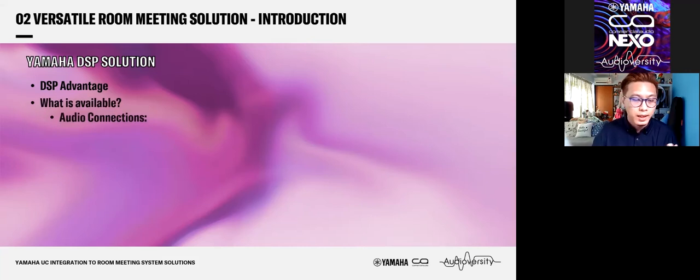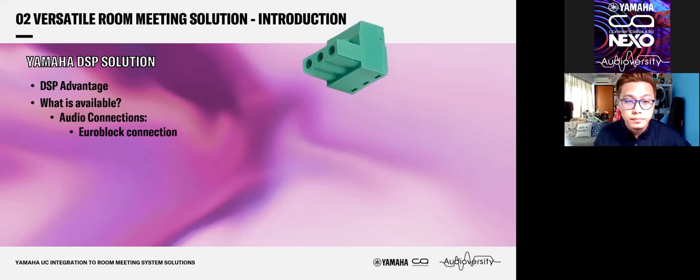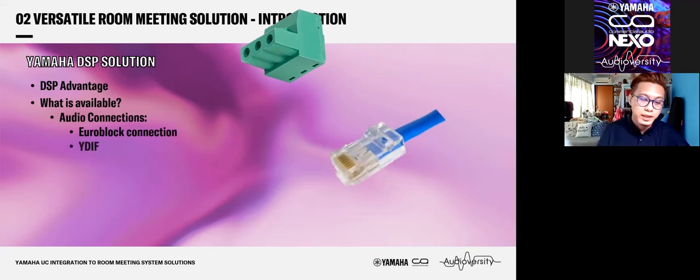First, what are the available audio connections for our DSP system? You can connect the input and output via this Phoenix connector, the Euroblock green connectors. And with Cat 5e and above, we recommend Cat 6, which is also very common now, we have our YDIF.